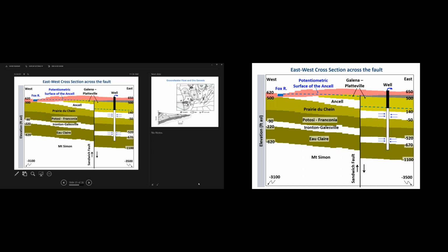But the flow is calculated always above, below, and within the layer. I'll show you more examples in glacial aquifers where you get what looks like all these little isolated sands because the layer is steeply dipping, but in reality it's calculating mass balance, even though they look completely offset and the elevations are completely offset. So I guess what I'm trying to say is MODFLOW doesn't recognize those elevations.